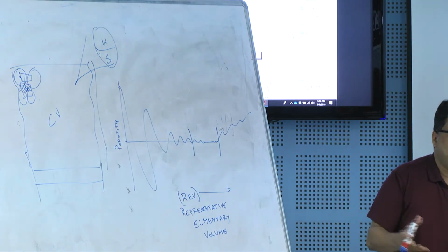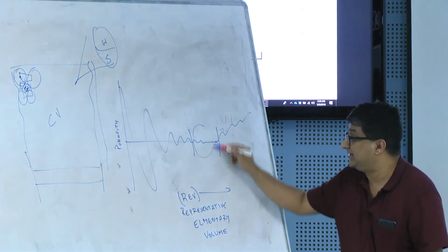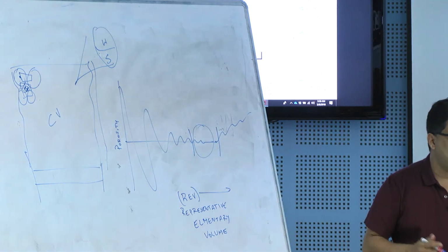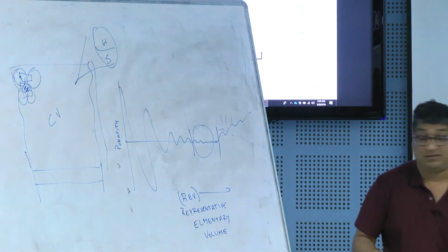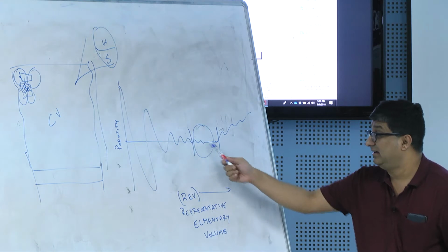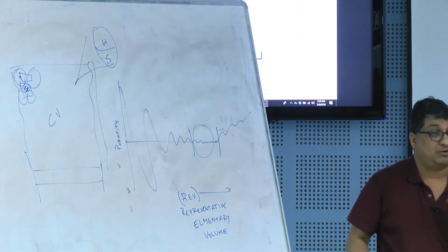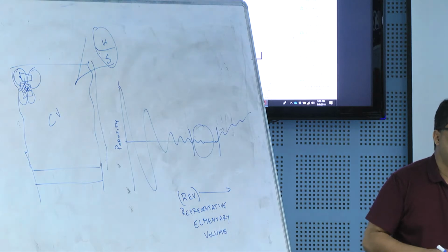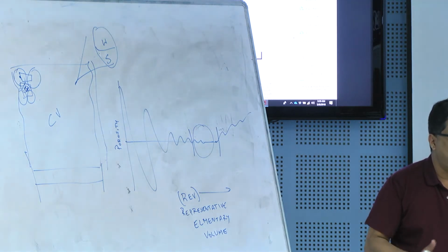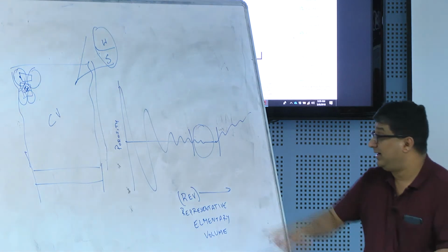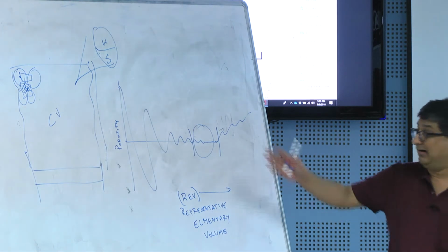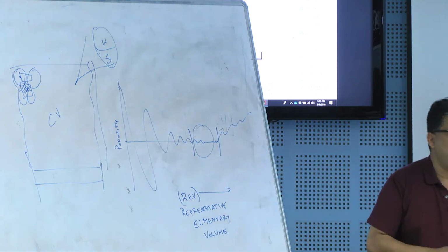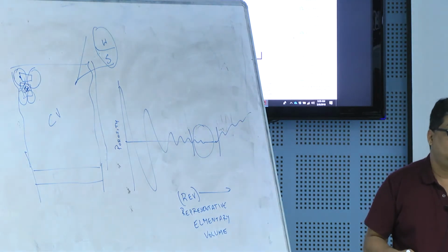Now, Darcy's law is valid at this scale. Okay, because Darcy's law, as I said, is based on some average properties. So the validity of Darcy's law lies in that REV being relatively constant. In other words, the porosity is roughly constant. So if you want to collect an aquifer sample, we need to take a sample equal to that REV. Okay. If you want to do modeling, the control volume of that model should be equal to that REV.